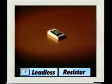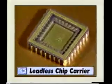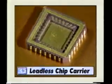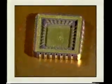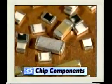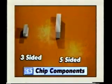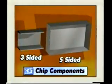Leadless components include chip components and the leadless chip carrier, called the LCC for short. The most common type of metallized termination component are chip components, with their 3- or 5-sided terminations at opposite ends of the component's body.